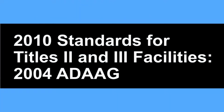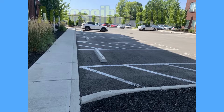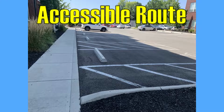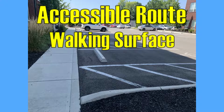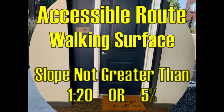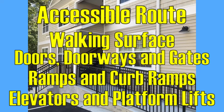Let's get started with the 2004 Architectural Guidelines, Chapter 4, Accessible Route, Technical Specifications. An accessible route will consist of one or more of the following components: walking surface with a running slope not steeper than 1 in 20, doorways, ramps, curb ramps, elevators, and platform lifts.